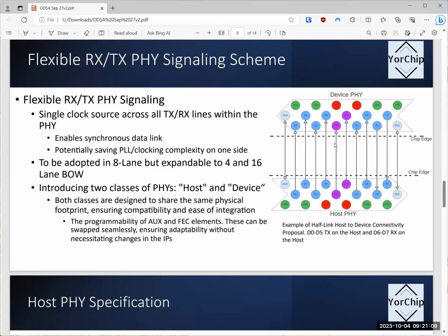So my timing sign-off, I actually have to consider for two scenarios, so that it can work in both ways. That adds additional considerations in the actual implementation where I have to sign off the timing, and I also consider both aspects, unless this is a very dedicated scenario.